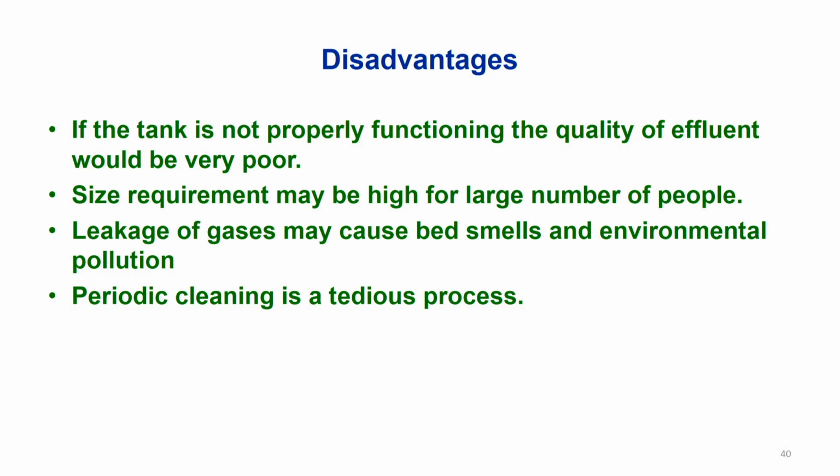Otherwise, pressure should not be allowed to form within the tank either, because methane is an explosive gas. If it is present in air between 5 to 15%, then it can explode. Periodic cleaning is a difficult task here.